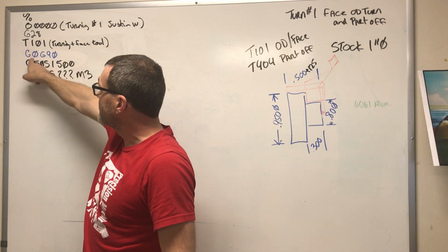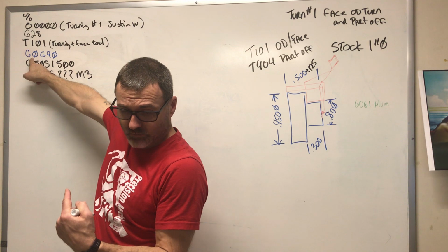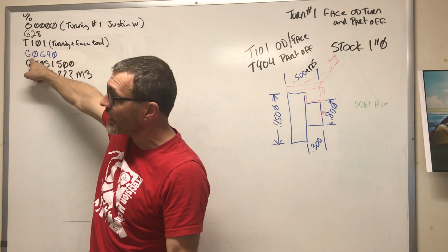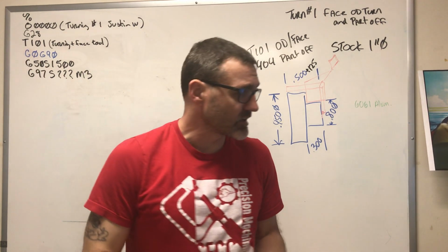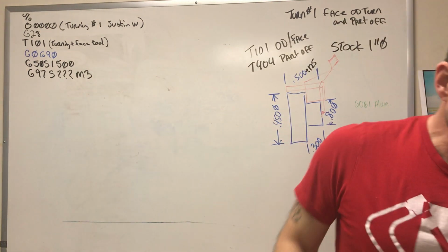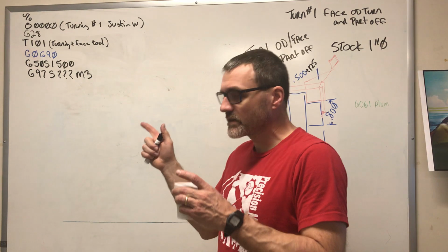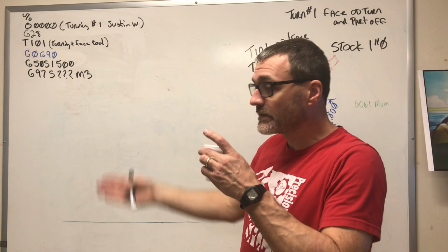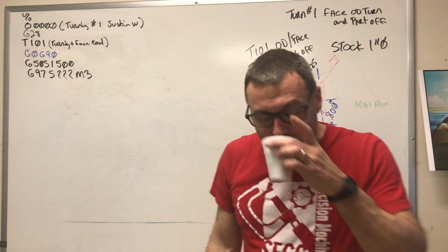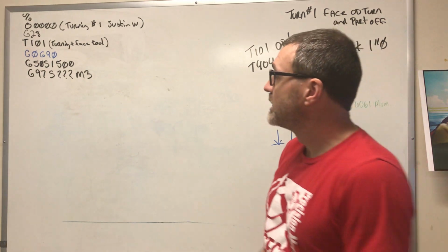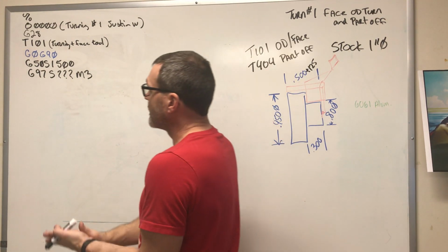Next one that I actually inserted in here, so this is why this is in blue. It doesn't follow the format that's on page 21 exactly, but it's pretty close. The reason why it's not on page 21 is because typically your machine is going to default to these things. It's going to default in absolute, and it's going to default in rapid mode. So those are modal.